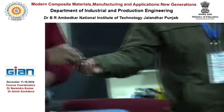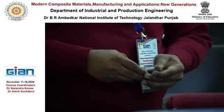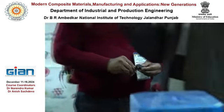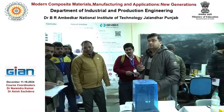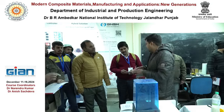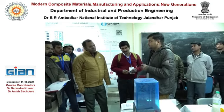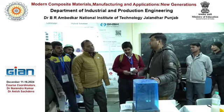See the surface finish, because yesterday I was talking about post processing, right? Why is post processing required? Sometimes it is required to finish the surfaces, but here in DLP you can get very good surface finish and you can minimize the requirement of post processing. So this is one advantage with DLP.